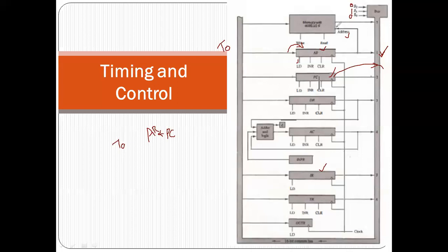We have the address of the memory to be read in the AR register, which is connected to the memory unit via address lines. Via these parallel address lines, the memory location is selected, and the corresponding 16-bit information has to be placed onto the common bus.